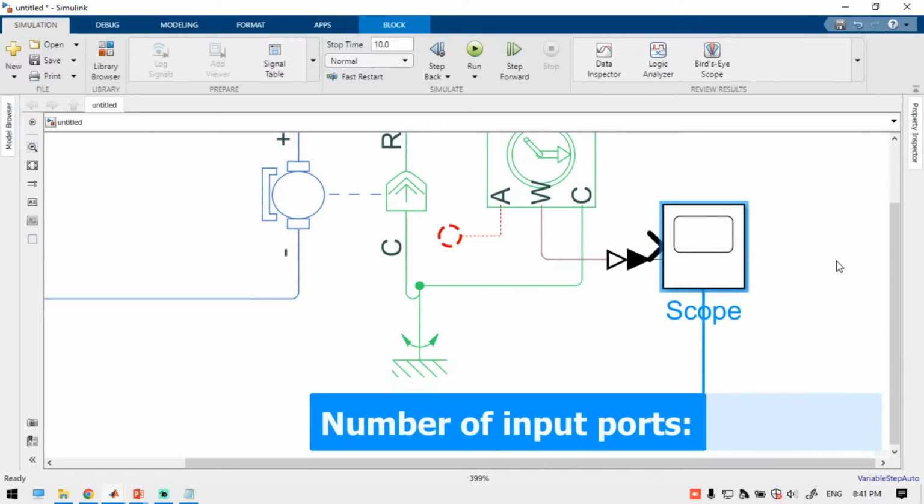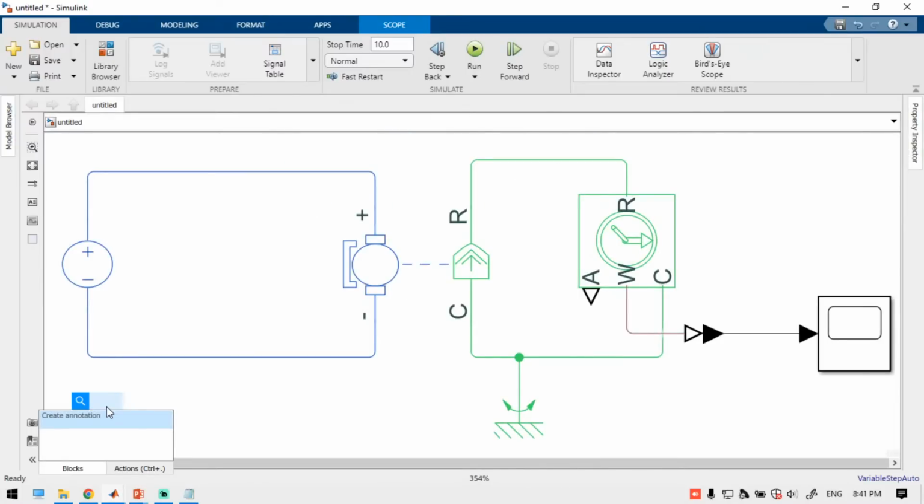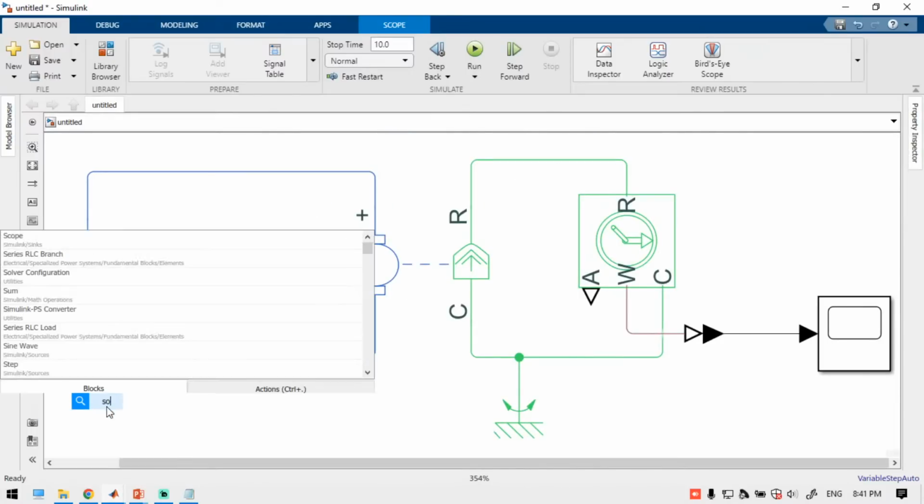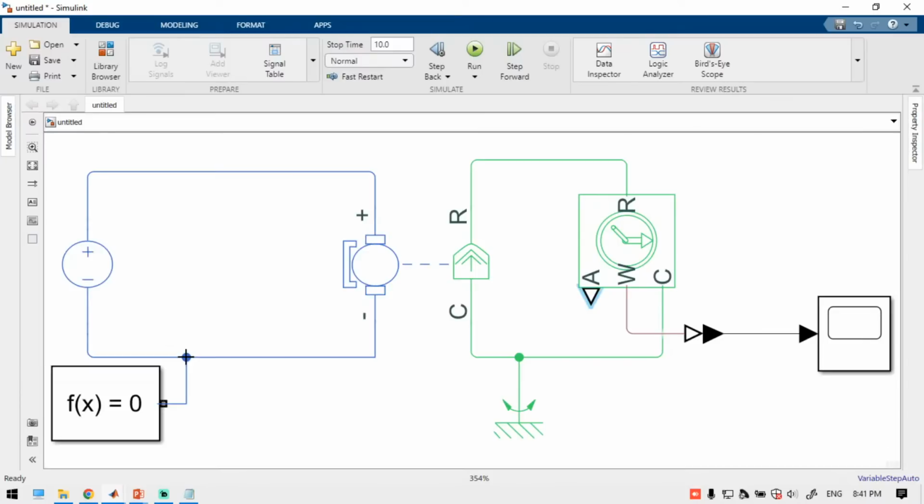Since all these components are Simscape components, we have to include that header file, the solver. Simply we can understand this as a header file. Just include it here, and here we should include the electrical reference, the ground plane. We have to add that at this moment.